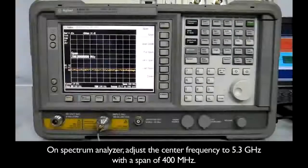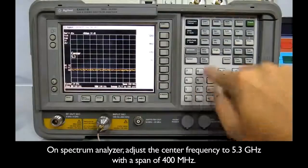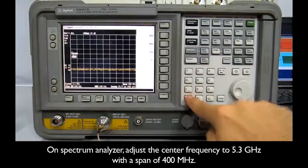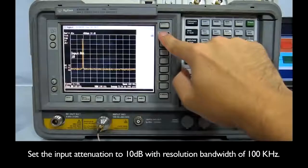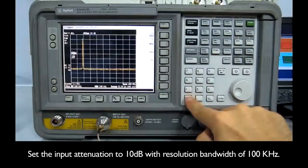On the spectrum analyzer, adjust the center frequency to 5.3 GHz with a span of 400 MHz. Set the input attenuation to 10 dB with resolution bandwidth of 100 kHz.